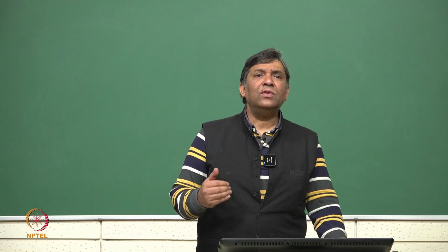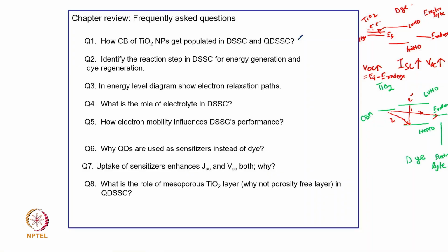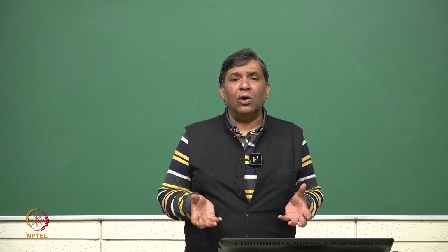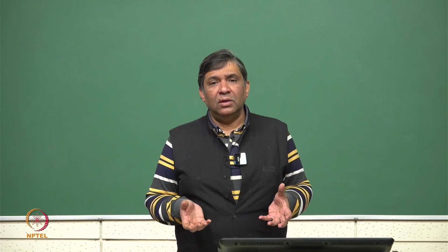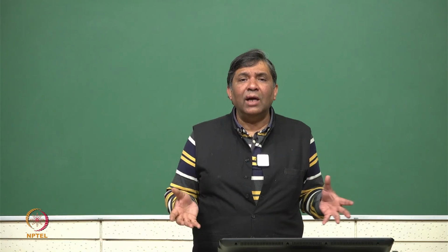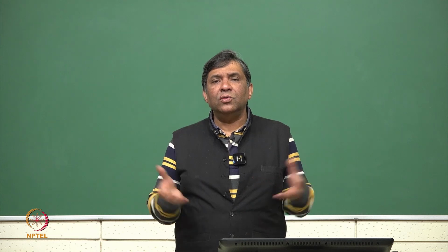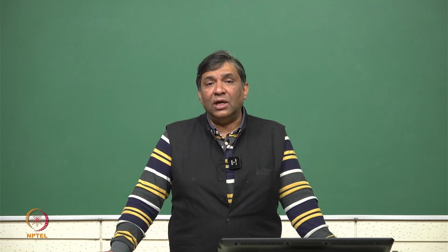Next question is, what is the role of mesoporous TiO2 layer? Why not porosity free layer in QDSSC? This is very simple, because if this is mesoporous, we can have large number of dye molecules which can be anchored. And unless we have large number of dye molecules attached with the TiO2, we cannot generate the adequate number of charge carriers.